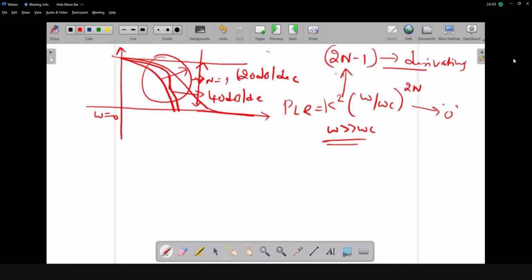So we have already seen the equal ripple filter. That is nothing but a kind of Chebyshev response. We already saw what the Chebyshev response is, and how the ripples are going to happen. So we'll be having 1 plus k square, that is the 3 dB level, and we have the ripples in this particular band, from 0 to 3 dB down, so minus 3 dB down.